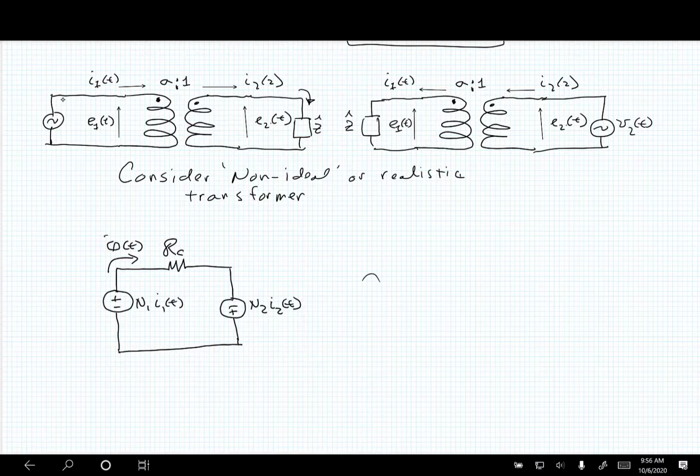Okay, so here's that magnetic circuit, but remember that we changed the direction of the MMF, the current. So what we did was I changed this, so it's like this. So now the flux coming out due to the secondary MMF would be opposing the flux from the primary MMF.